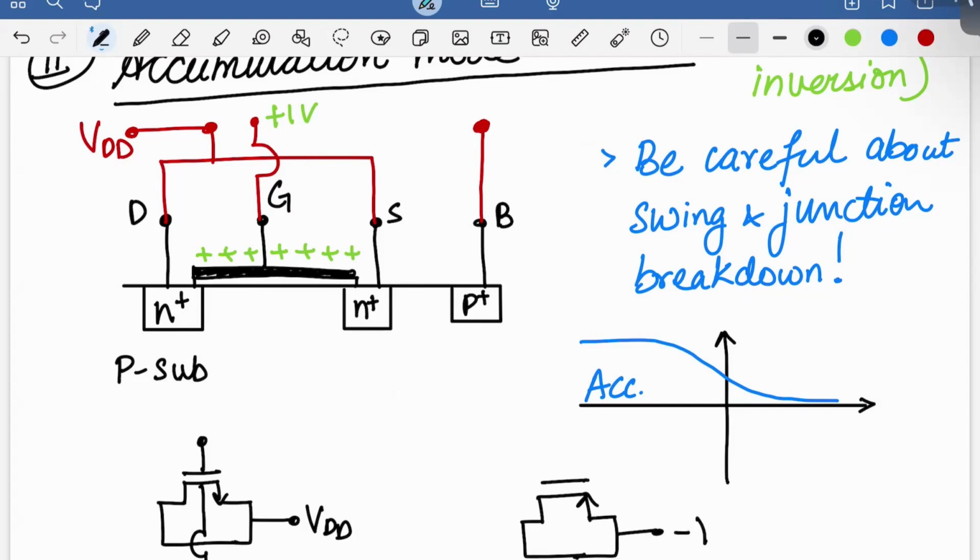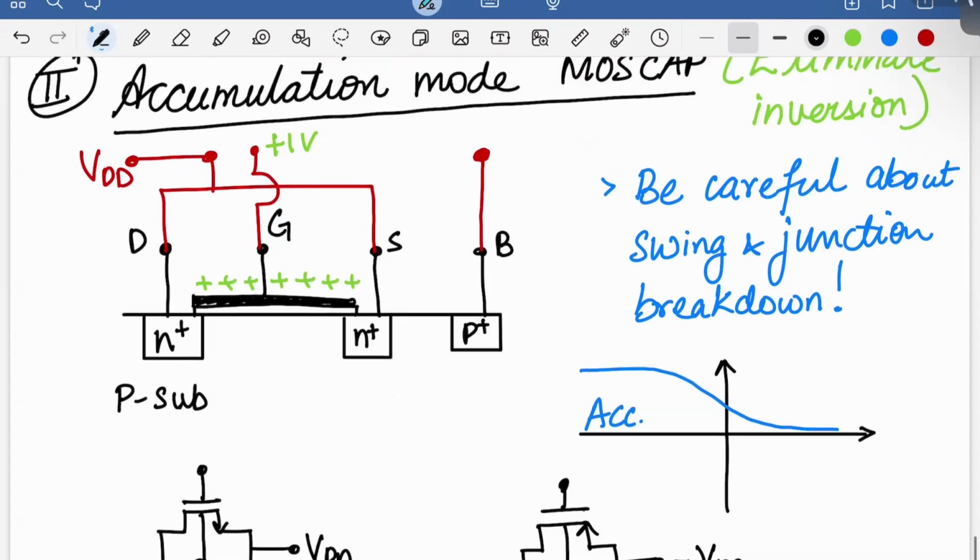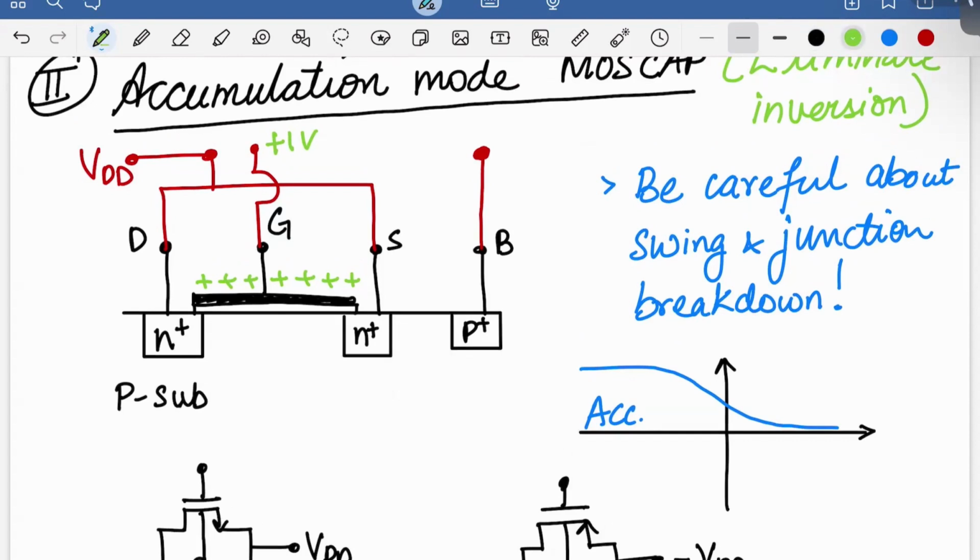Of course, now you would connect to minus VDD, and you can think about the layout and see in the layout what minus VDD actually does for a PMOS device, right? And you'll use the body contact as part of the cap. So this is accumulation mode PMOS. Okay, so this still has the same problem of that parasitic cap, or parasitic resistance, right? Because your resistance out here, and then you have this small cap here, and that resistance can be large.